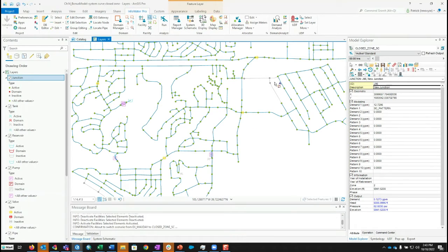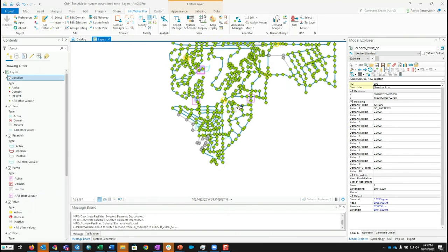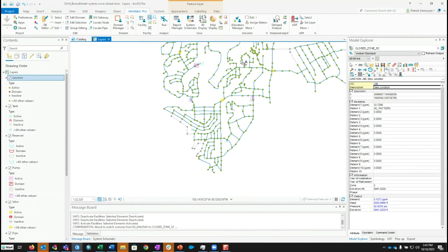It's not often the case, but it's one of the unusual things in here because we're in a PRV zone. Those PRVs are setting the hydraulic grade line on the suction side of this pump station. And then on the discharge side, there's obviously no tank, just this dummy tank that's keeping a fixed hydraulic grade line, but it's not filling and draining. It's just keeping a constant HGL.